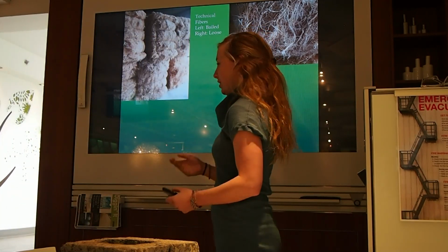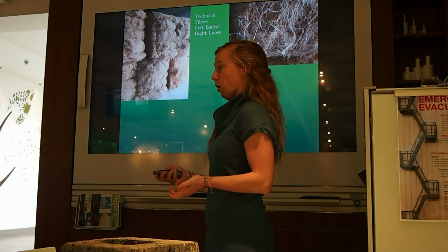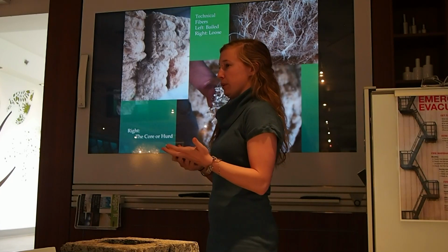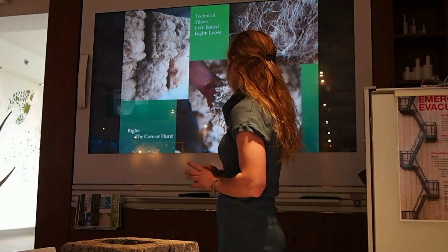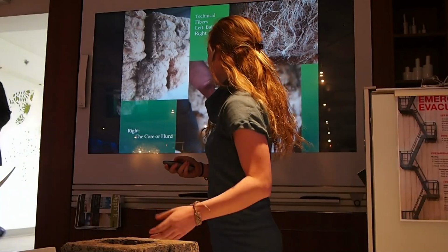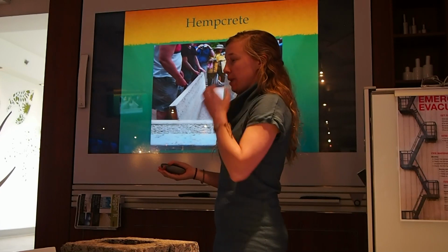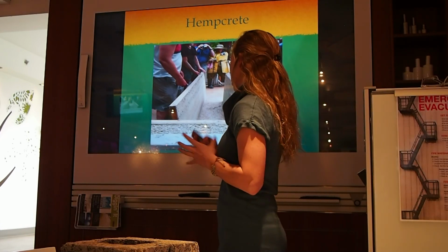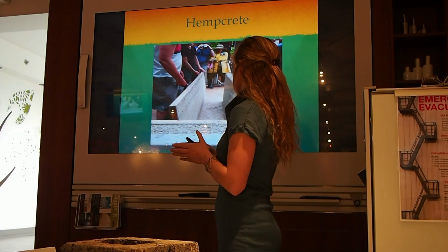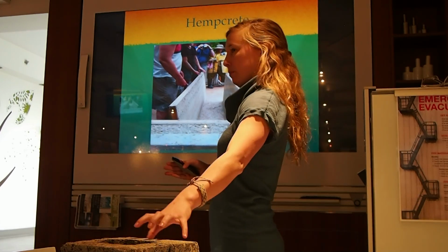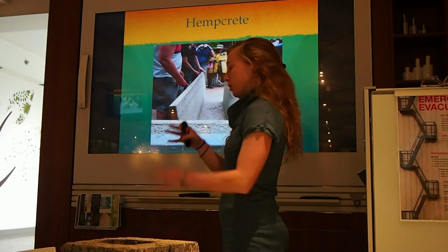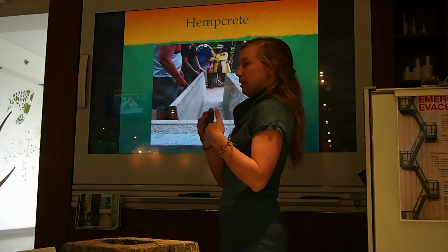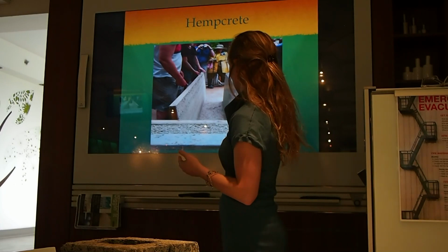So another part of the hemp fiber is the core, or the hurd. This is what a lot of the construction has been using in the recent past and current state, and it's what a lot of the European houses are made out of. When you mix the hemp hurd with a lime binder, it's called Hempcrete. In Europe, they originally started modeling these houses with a timber frame because it doesn't have load-bearing strength like those products do. So you would create the timber frame and then tamp the lime binder and hemp hurd within movable formwork, and then you have a wall.